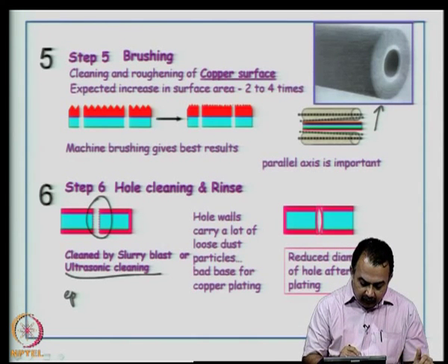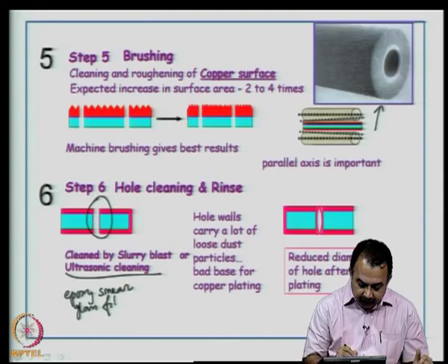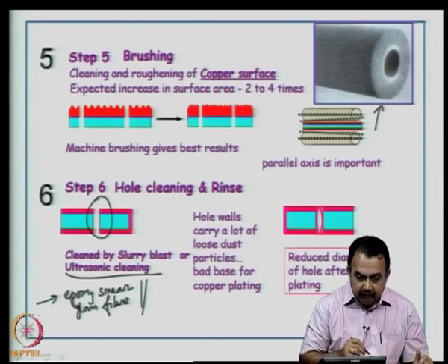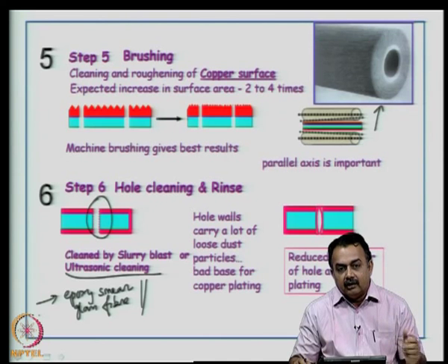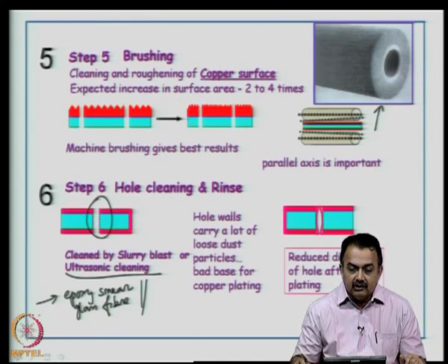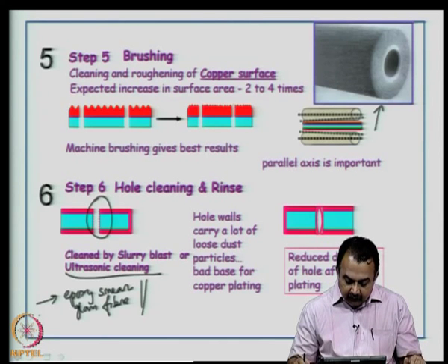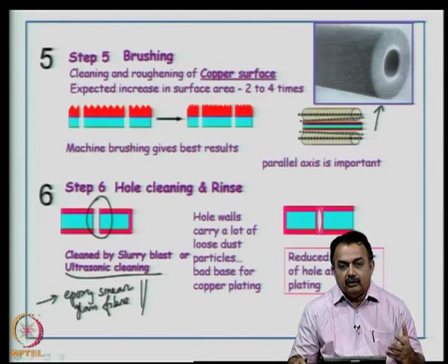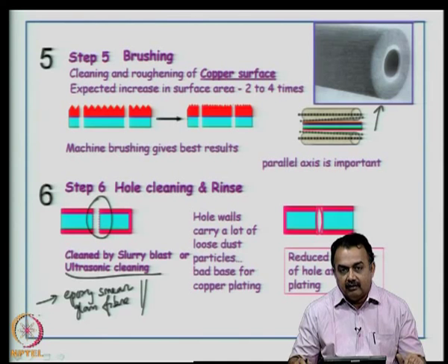So, what you will basically see after drilling is an epoxy smear or a glass fiber which has to be removed. Smear is basically coming from the melting of the resin during the drilling process and a quick solidification. They can also carry a lot of loose dust particles that come from the drilling.